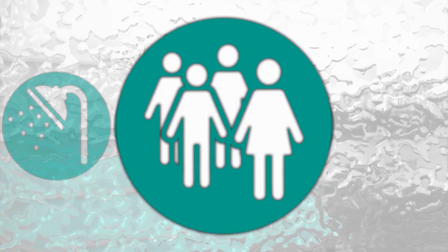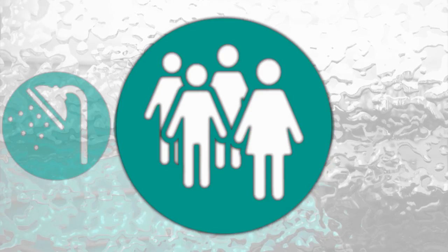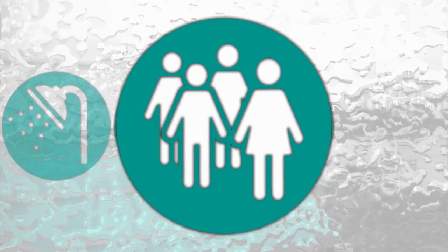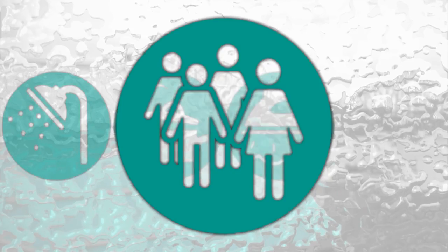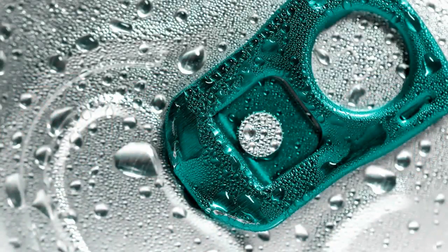Finally, the building occupants themselves produce a lot of moisture through breathing and sweating. Even while sleeping, this represents a substantial source of moisture, and activities such as sport produce significantly higher moisture loads. When considering condensation control strategies, the activities taking place in the building are among the most important factors. Another common example of condensation is cold drinks cans on a warm day, but how and where does condensation occur in the context of buildings?